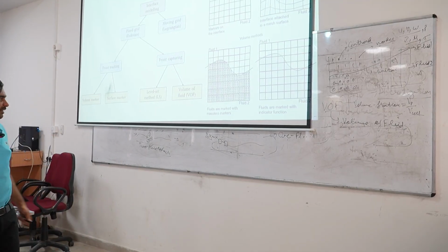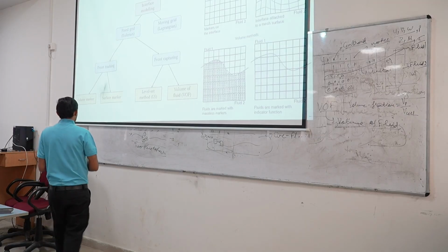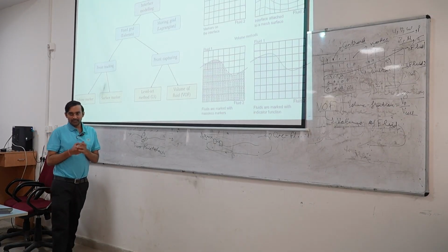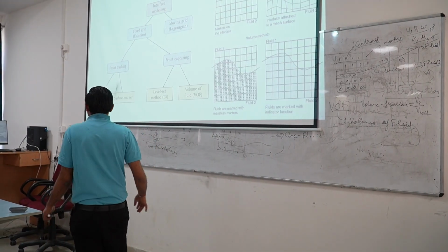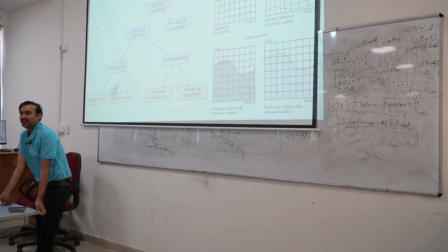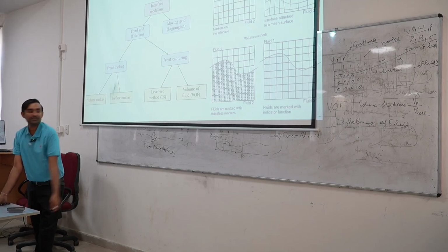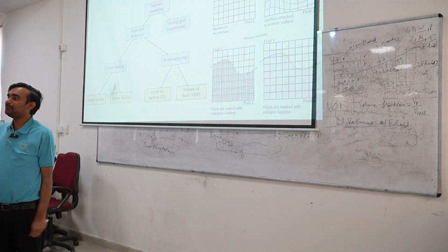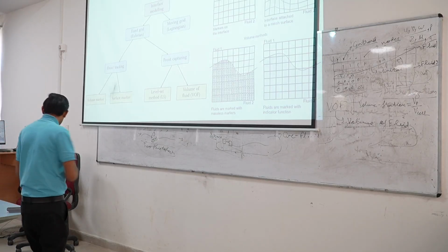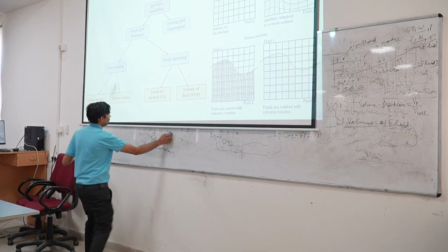For that purpose, we define one equation which will be an addition to the momentum and continuity equations, and that particular equation is called advection of volume fraction.